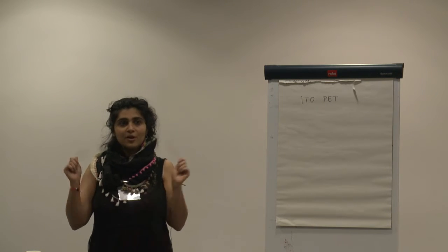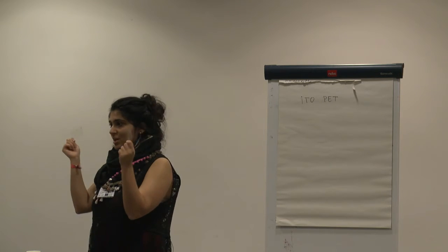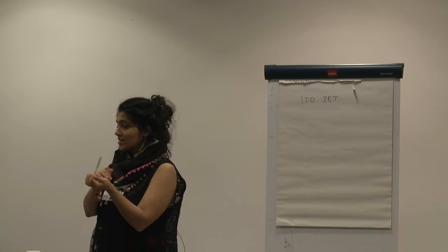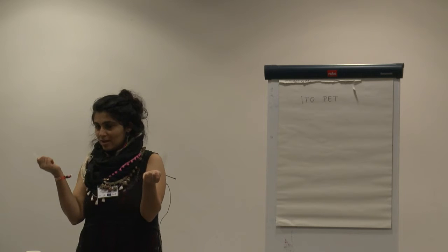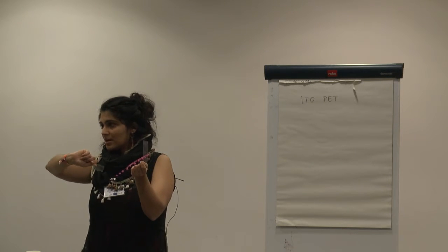So you can have glass-coated ITO and you can have PET-coated ITO. We're trying to use paper and PET because we're trying to make these things disposable. Ideally, you have a glass substrate. You can have chromium glass, but that requires vapor deposition, very expensive tools that we don't have in a computer science lab. However, we can buy a bunch of chemicals and etch it using ITO PET.